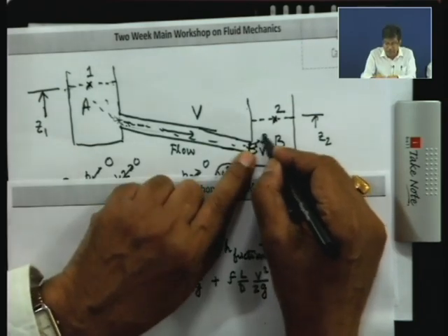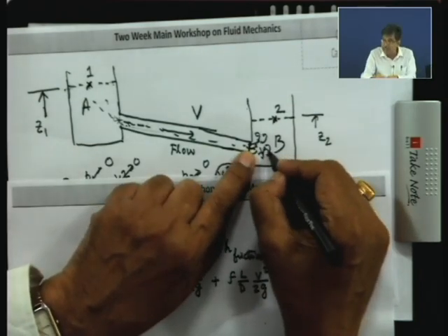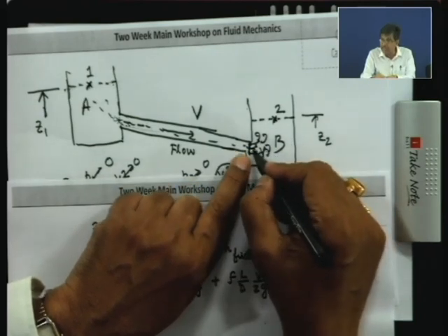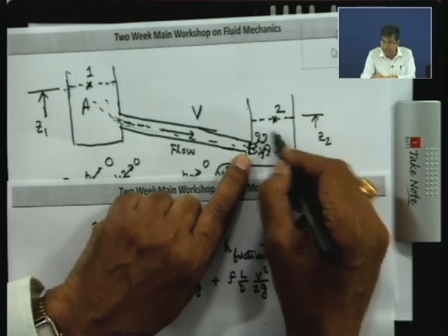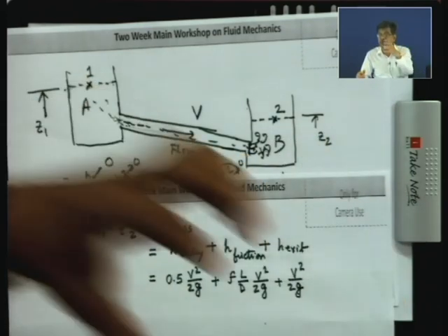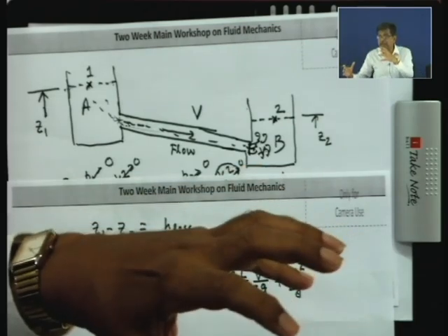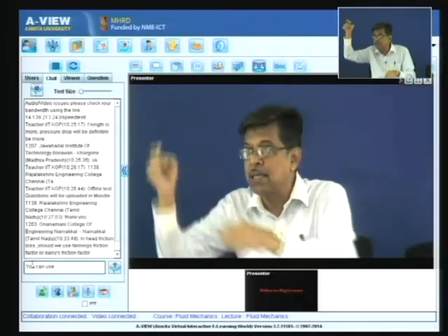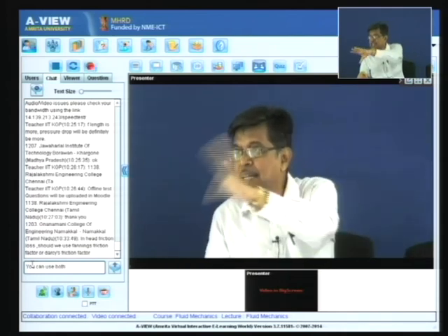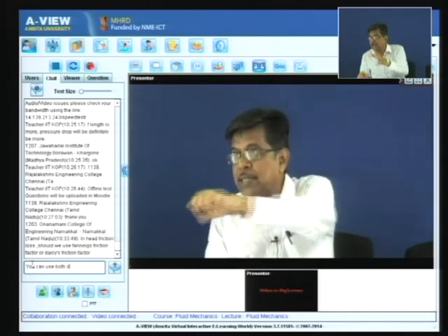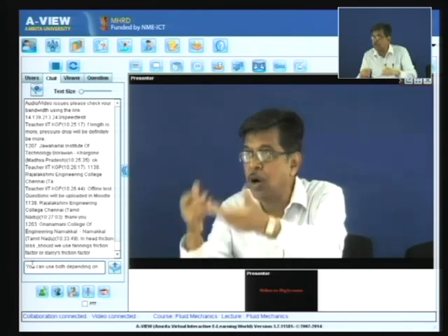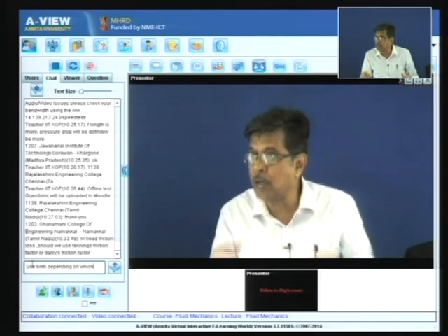This kinetic energy is ultimately dissipated in the form of eddies and increases the intermolecular energy. That means this entire kinetic energy is lost, degraded or dissipated through intermolecular energy. A high speed flow comes, and if you arrest it in a big chamber, the fluid comes to rest. If you measure, the temperature will increase. The kinetic energy is converted into intermolecular energy, purely by fluid friction at the molecular level.